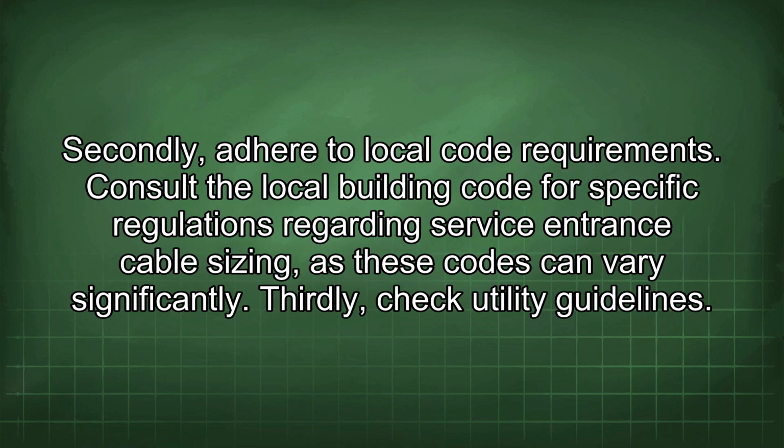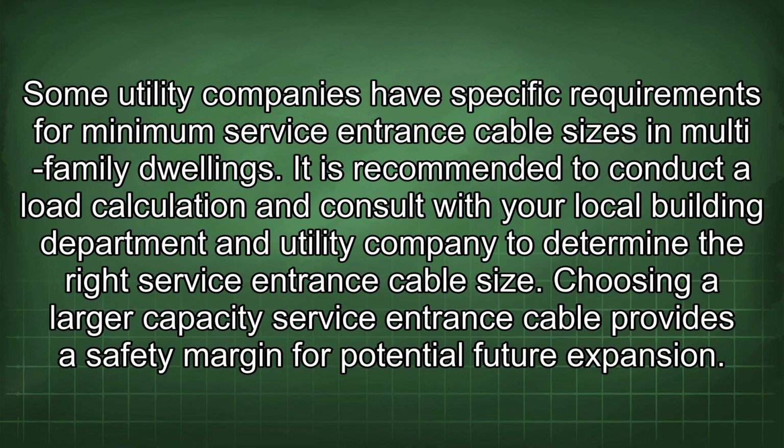Thirdly, check utility guidelines. Some utility companies have specific requirements for minimum service entrance cable sizes in multi-family dwellings. It is recommended to conduct a load calculation and consult with your local building department and utility company to determine the right service entrance cable size. Choosing a larger capacity service entrance cable provides a safety margin for potential future expansion.